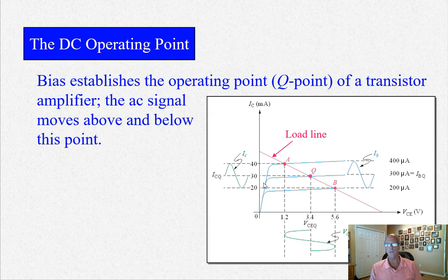Notice the amplification here. We're going from 200 microamps to 400 microamps on the base, and the collector is going from 20 milliamps, this is, to 40 milliamps.